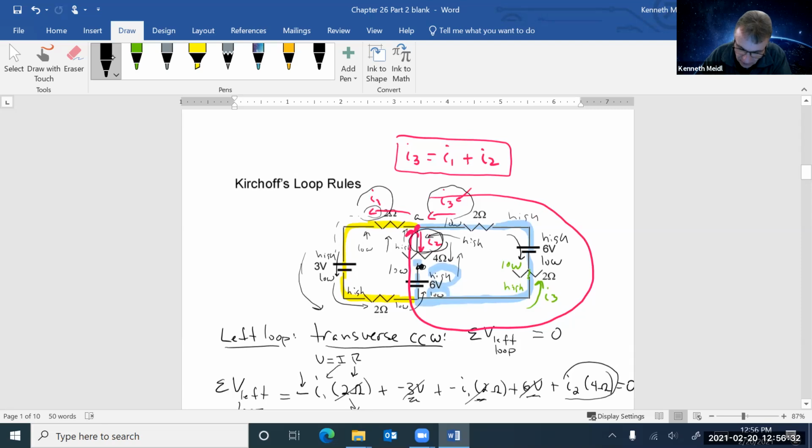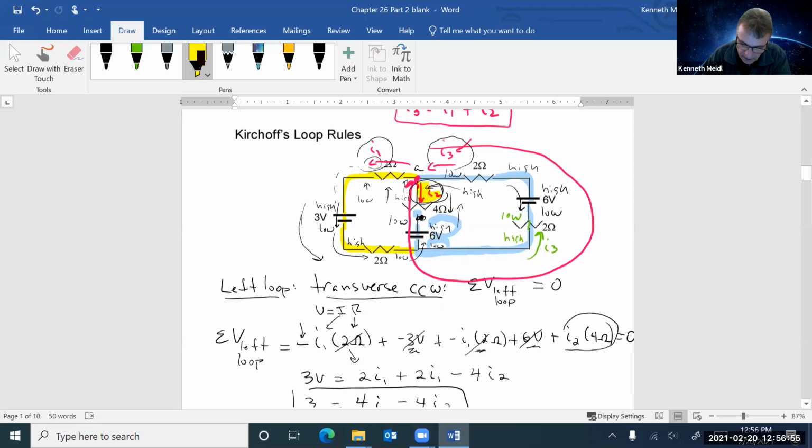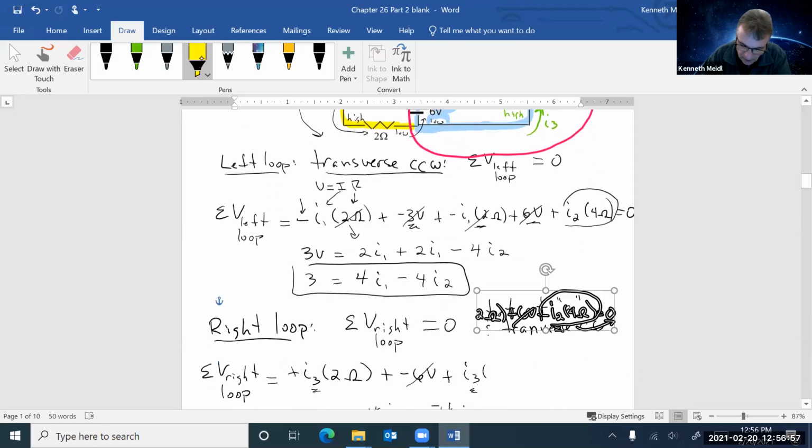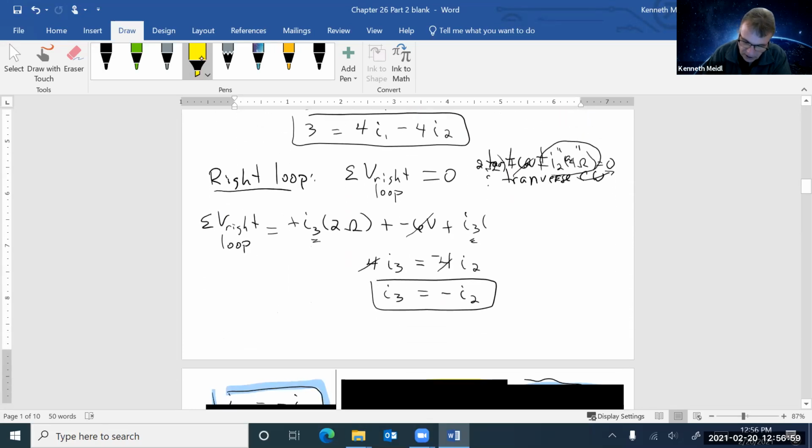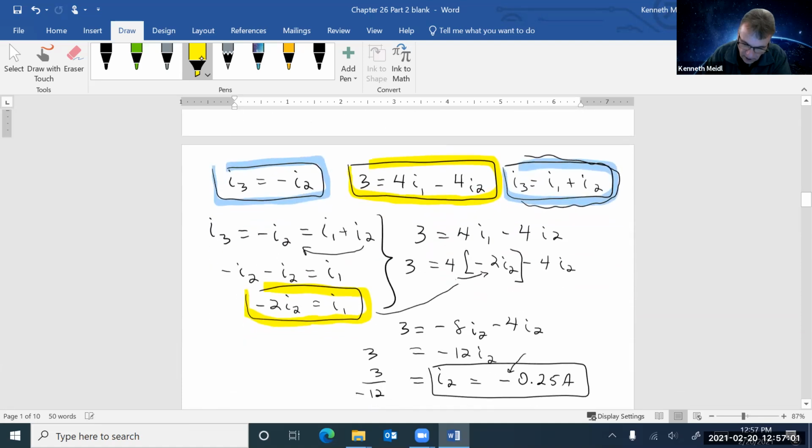this calculation, that I chose I2 to have a certain direction, and I2 is sitting right here. Okay, and so I said, well, it's really leaving that junction. And my calculations say, no, it's really going in the opposite direction. Okay, so it's really coming up. And so my direction is not quite right, but that's okay. So that just means that the direction is opposite of what I've got here.